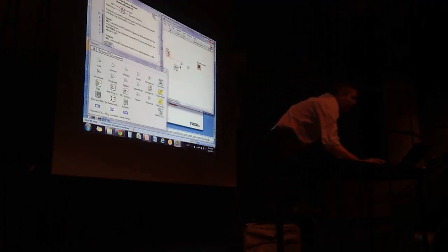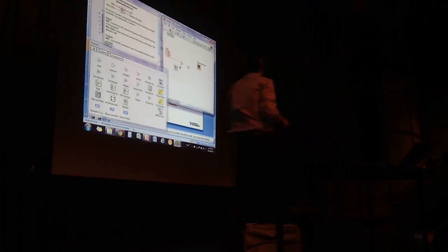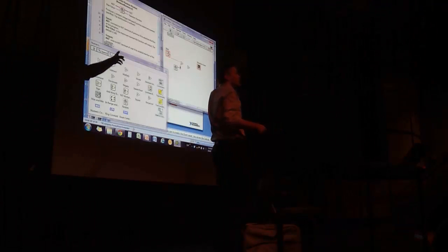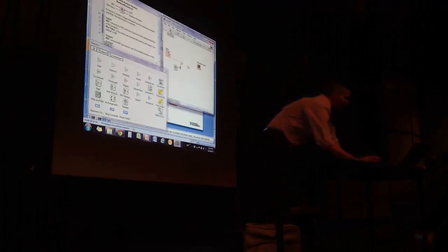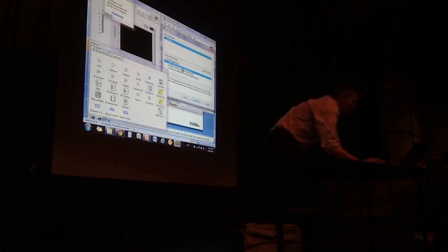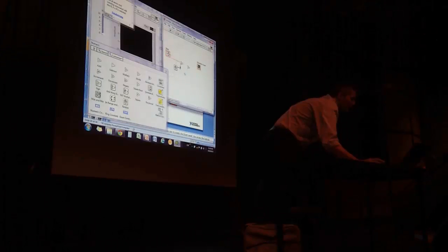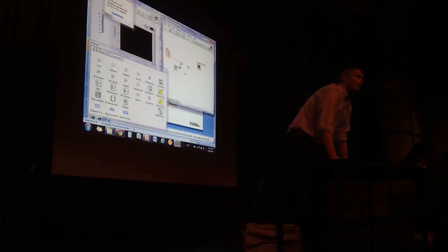And you see this right away. This up here is the start button, and I will go into that a little bit more. That's broken, so it tells me I have an error here. So I can just directly click on it and see, yeah, this is an unwired terminal. The multiplier contains two terminals of different types that you have connected. So you get this information right away. You can click on it, and it shows you directly where it is.